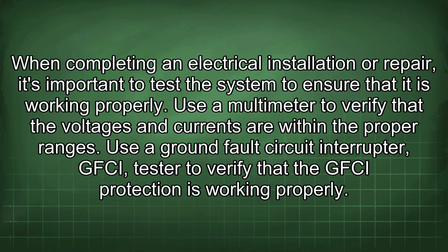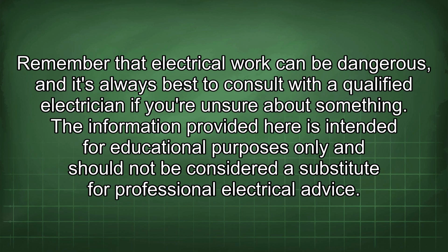Use a multimeter to verify that the voltages and currents are within the proper ranges. Use a ground fault circuit interrupter (GFCI) tester to verify that the GFCI protection is working properly. Remember that electrical work can be dangerous, and it's always best to consult with a qualified electrician if you're unsure about something. The information provided here is intended for educational purposes only and should not be considered a substitute for